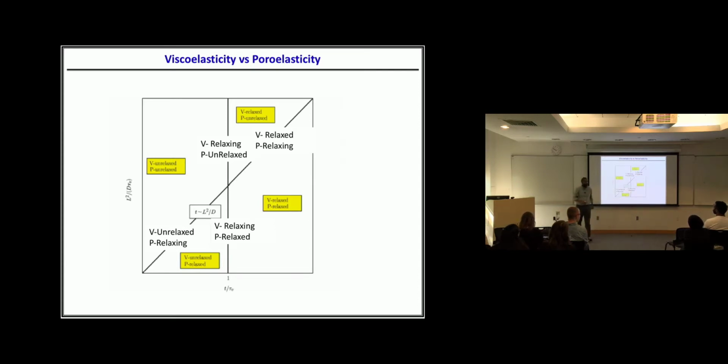Yes. So what L is not the total size of the sample, but some unit size within the material? L is the size of the sample, or the size of the region you're loading, because you need to expel the fluid from a region of size L. It's not a characteristic size of the material, it has to do with the size of the sample. Okay, all right.